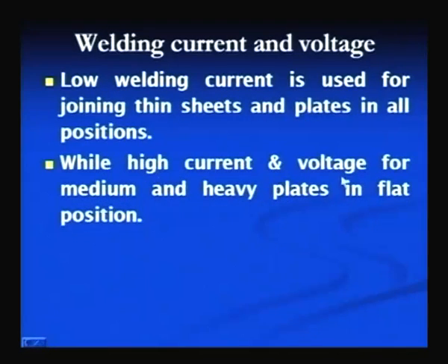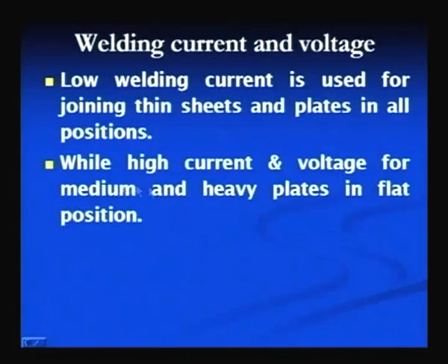While the high current and the high voltages are used for welding of thick plates in flat position, there are two regions. One is joining of heavy plates, which needs the high current for high deposition rates and for high penetration, and at the same time the fluidity of the weld pool in flat position does not create any problem.